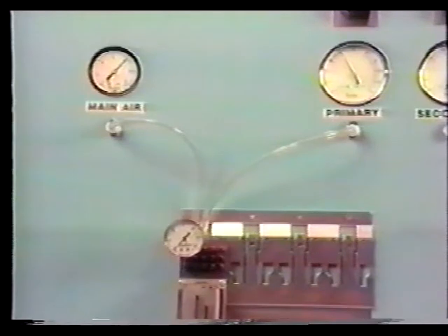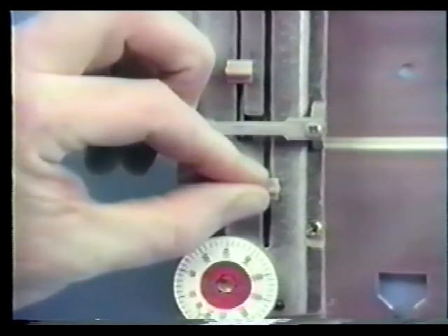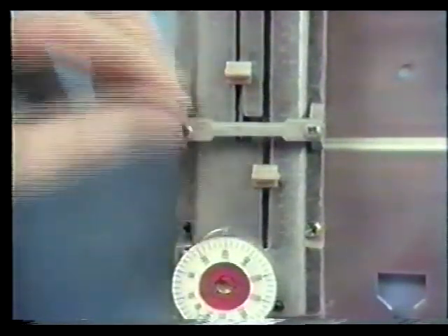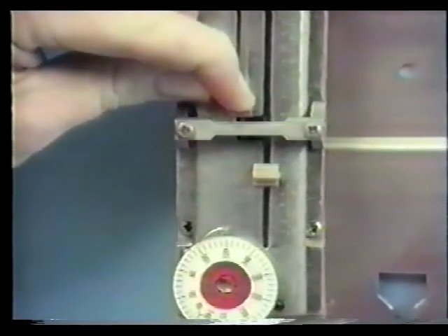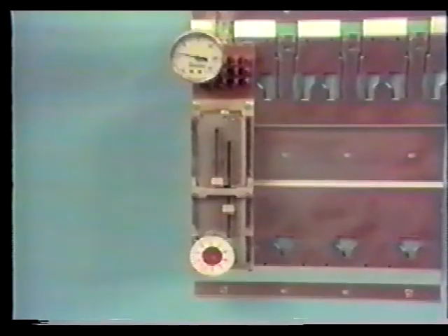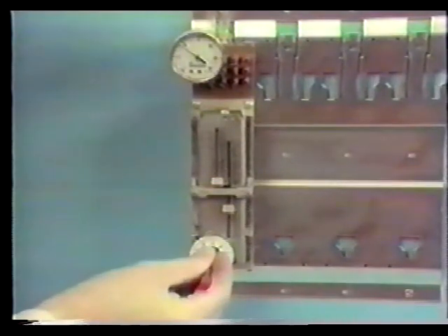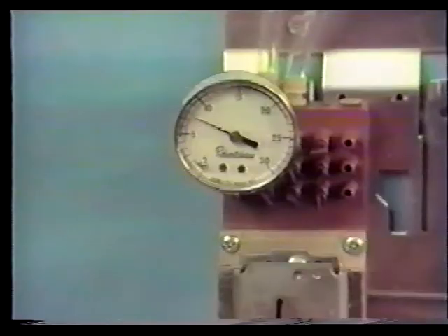To calibrate a receiver controller in the field, it must be calibrated to the transmitter input. Set the throttling range slide to the desired point. Set the authority slide to 10% or the minimum setting. Note the input pressure or reference temperature on the primary input receiver gauge. Adjust the control point adjustment with the calibration tool to match the temperature reading by adjusting the branch output pressure to 9 psig or the midpoint of the spring range.